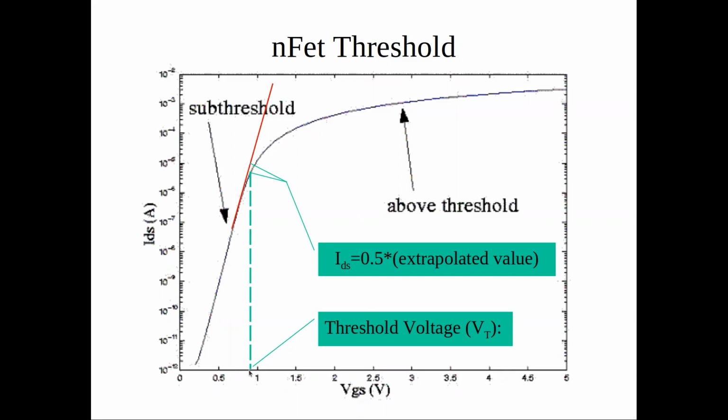And as I told you, depending on the process, that also depends. You can see it depends on the slope and it depends on I0. So it depends on the process parameters. It's something typically between 0.7 and 0.9 volts. It's another thing that you can consider as constant. So if you have inputs to your transistor that are below 0.8 volts, you're pretty sure you're in the weak inversion regime. You're in subthreshold. If you have inputs that are above 1 volt, you're definitely in strong inversion.